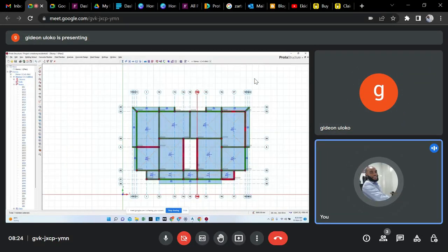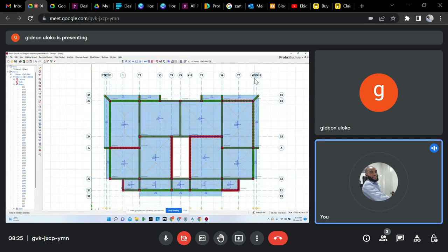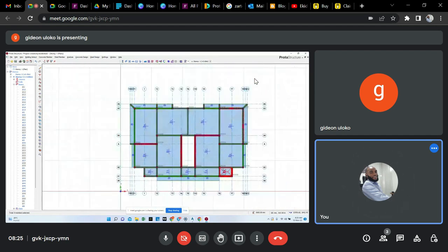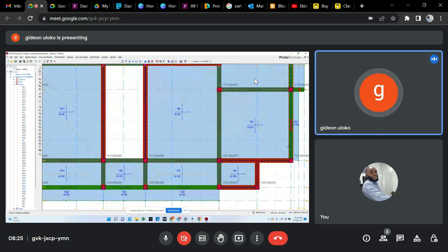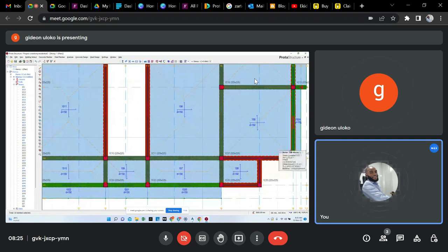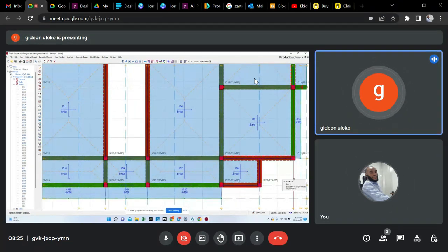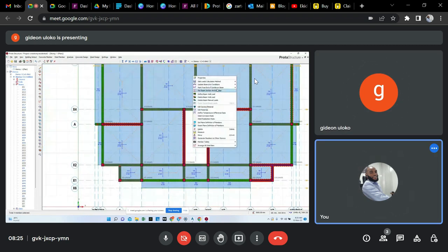Then also on grid line 4, the end of grid line 4, right hand side should be hinged. Sorry, S4, grid line S4. Right hand side, yes, that one. Also on grid line S2, the J end should be hinged. S2. Yes, this one, that one too. No, that one is at I. Don't choose that vertical one. Select that vertical one on the left hand side, because it's down here. Exactly. So now apply hinge first, then after I will check.